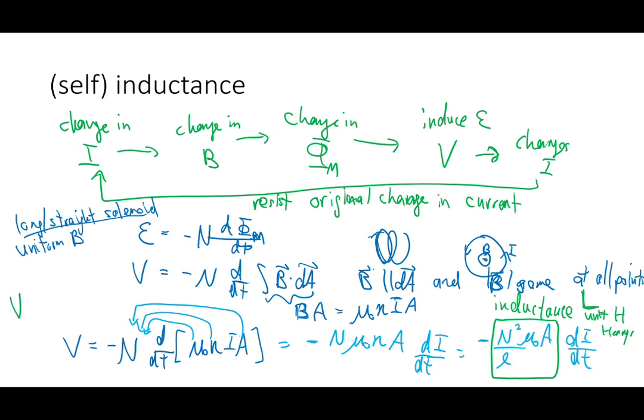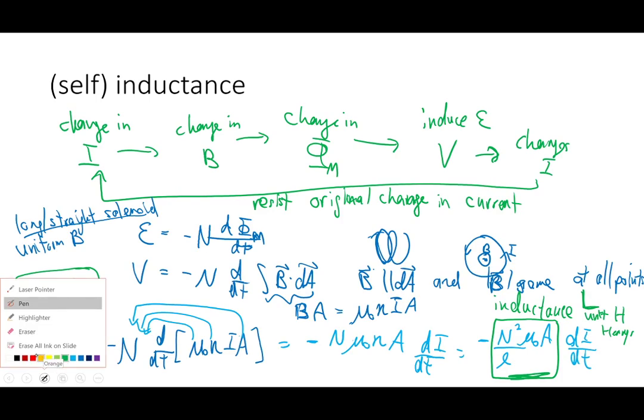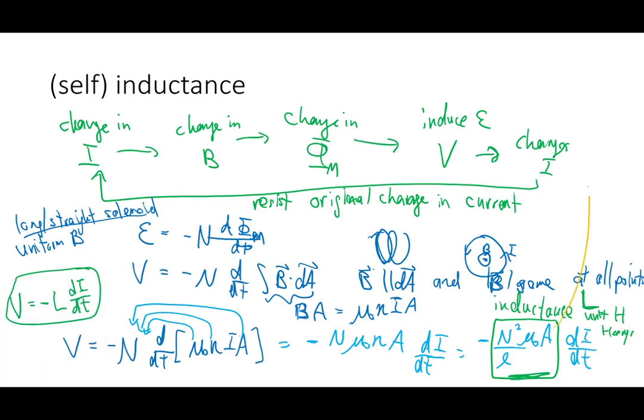So what we have is a governing equation for the inductor that can then be written as such. This particular expression over here happens to be how you would calculate the inductance of a long straight coil given the geometry of a long straight coil. Just at the risk of overloading this slide here, you can also have an alternate form where we use the loop density instead. So we put the L on top as a result. So that's an alternate form. They're both equivalent.